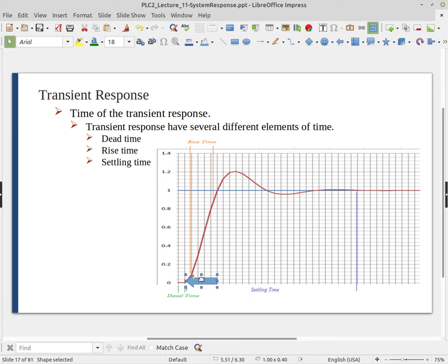For example, if you're moving gears or running something with a chain, there's slack in the chain that you have to take up before you actually see the system respond. So there are some mechanical effects for dead time, and also some delay built into any digital computer response.